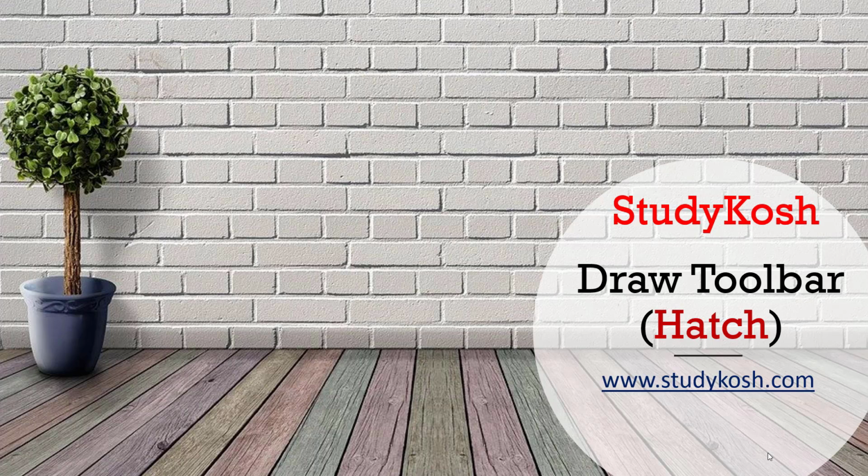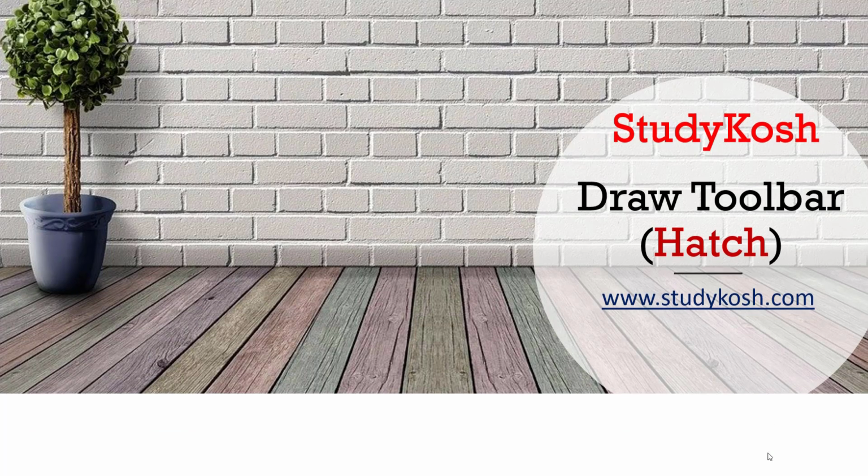The next tool that we are going to study today is Hatch. This is again a part of Draw Toolbar and might be a new term for most of you. Hatch is basically, as you can see in the background, there's a wall, there is a floor. Both have different patterns. So in AutoCAD, such patterns are applied using Hatch tool. It is very interesting to give different colors, different patterns, different kinds of shapes to the hatch.